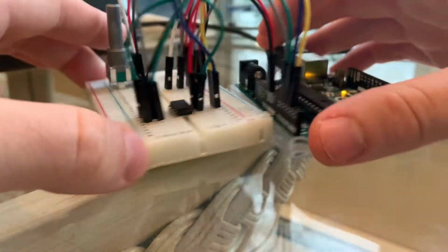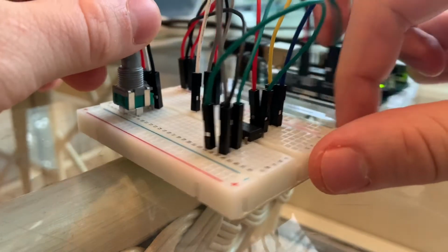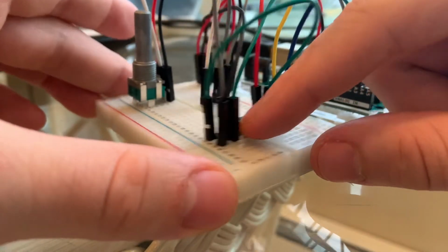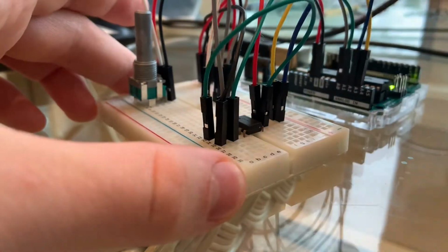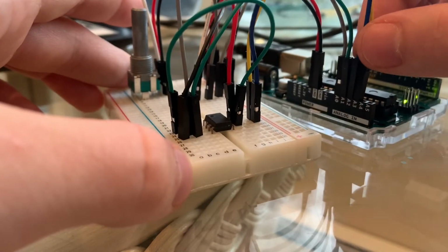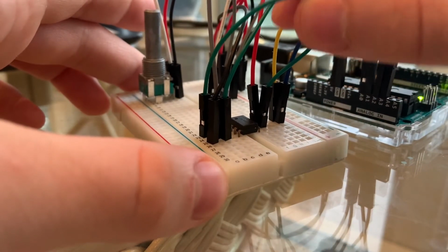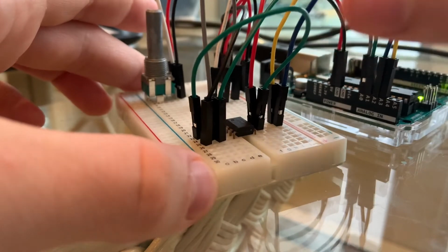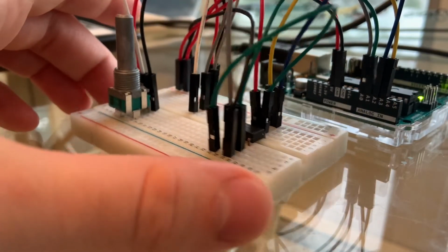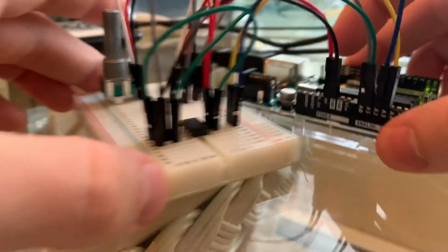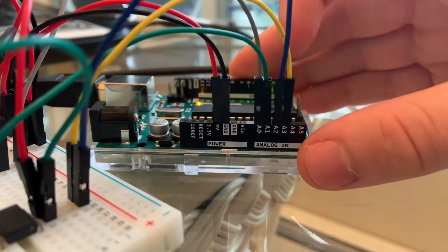All right, so for exercise 2, we're going to be looking into our circuit here real quick. We got this potentiometer, which controls V in for our op amp here. We have the green wires, which represent V minus. We have the yellow wire, which is reading V plus. The blue wires are reading V out, which actually equals V minus. And then we have the white wire here, which is actually gray because I ran out of white wires, but the white wire is reading V in. We have our 4 analog inputs here, and each of them is reading those voltages respectively.